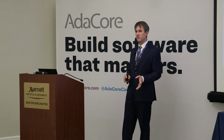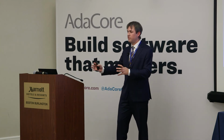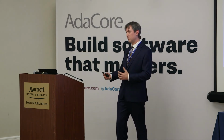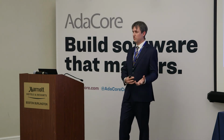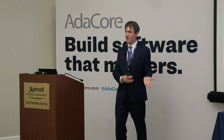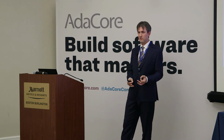And innocuity is kind of an odd duck. So innocuity is really focusing on extraneous behavior. It's really asking you if you've incorporated COTS, or if you're building a component that's meant to be COTS, it's likely the case that there is some piece of the functionality that's not actually required by your system. And this extraneous functionality could undercut your safety assessment, and so you need to look at it. And that's what innocuity asks you to do. It asks you to look at any kind of extraneous functionality that you might have and ensure that it doesn't violate your safety.